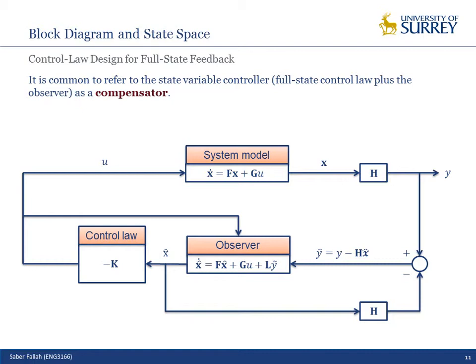So it is based on this relation. We can't calculate the X dot directly because it magnifies the errors. We need to use a 5th or 6th order differentiator. If you look at the paper, the references I gave you, you see the differentiator to estimate Z dot S minus Z dot U. But for Zs and Z dot S, because they are absolute displacement and absolute velocity, we don't have any sensor to measure them. How can we estimate them?